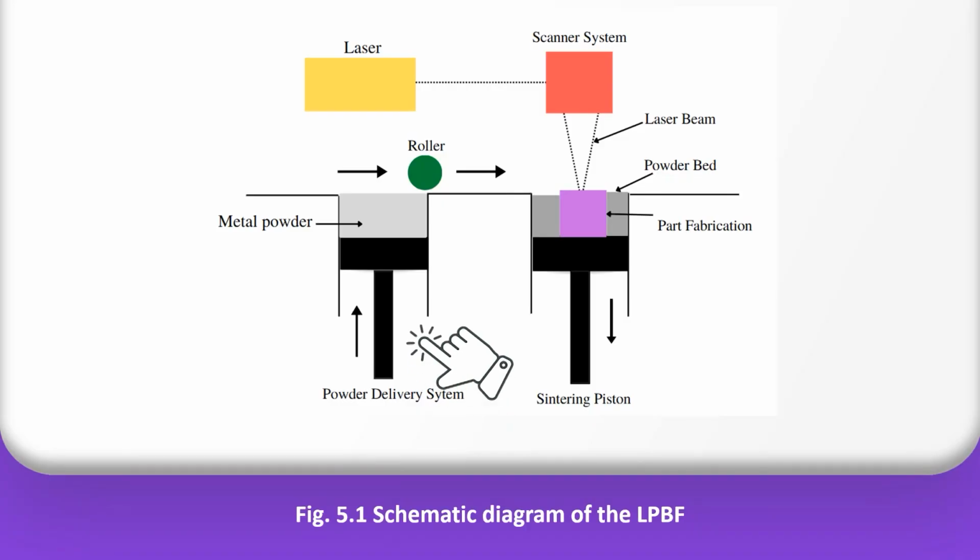Then I have a plunger which lifts this powder over here. Then there is a roller which spreads this material over the platform, right? So the material is deposited over here. As a thumb rule, if I put a material, let us say 3 mm, after the roller passes over here the thickness becomes 1 mm. Although we have some settings for how much compaction we want, for these types of printers 3:1 compaction is most commonly used, right?